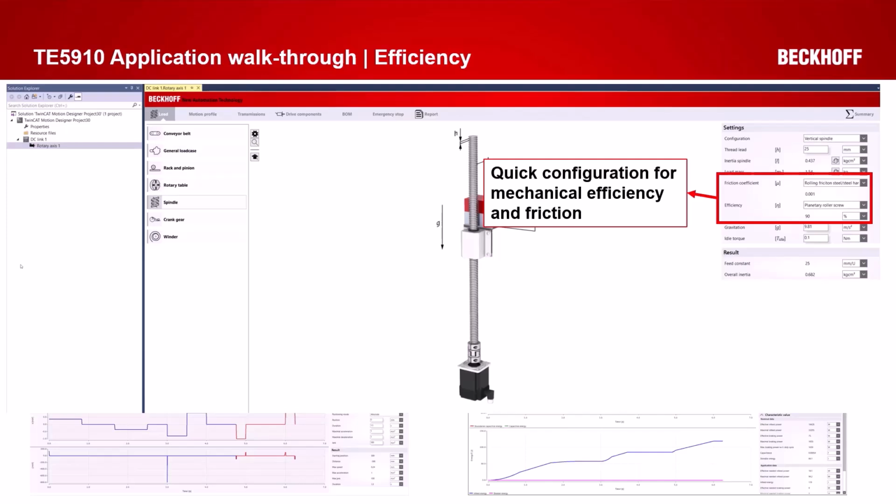And sometimes there's efficiencies just for standard mechanical devices, because maybe you know that you're working with a roller screw. Maybe you're working with a ball screw. Those have known efficiency calculations, and we offer a simple pull down. But even if you do know these calculations, because you're getting them from elsewhere, you can manually enter these values as well.